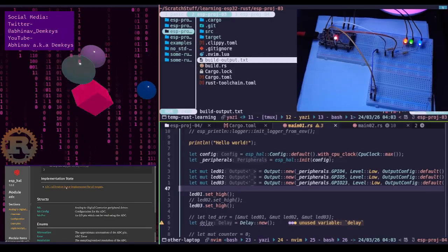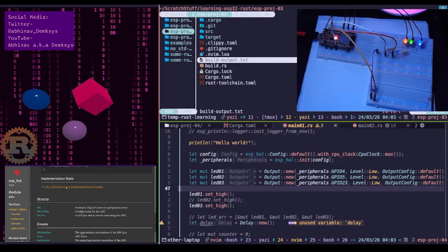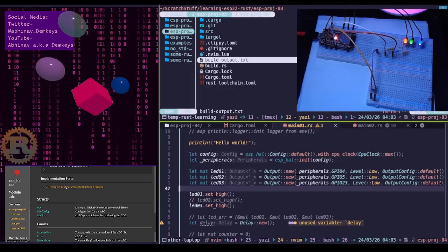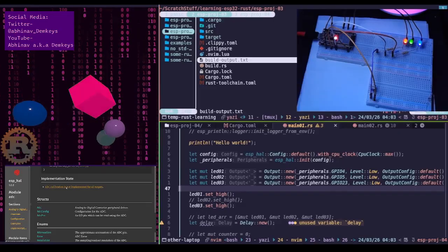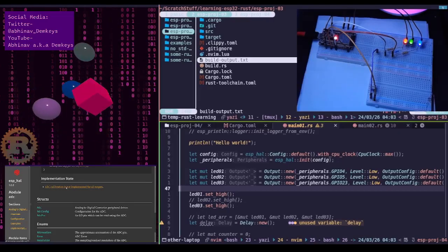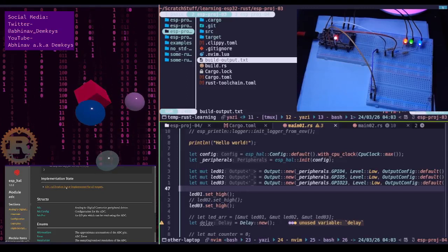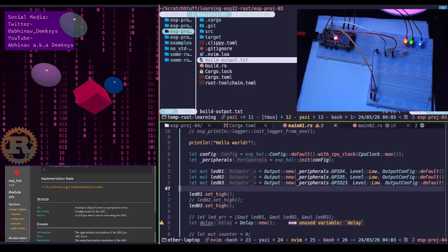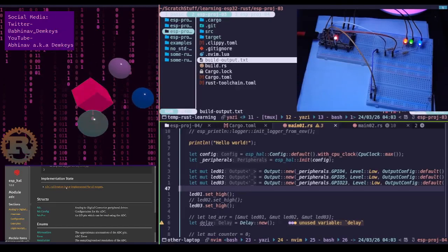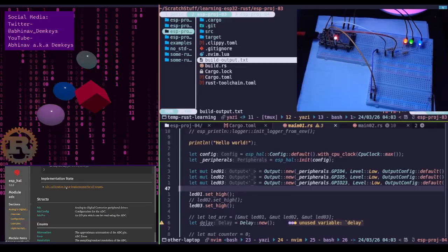Okay, then we have 2-point calibration. The effort is medium, but the accuracy is high. So you measure two known voltages and calculate your own y equals mx plus b. So you plot your own line for this. But didn't you mention earlier that it's non-linear? Yeah. Okay.